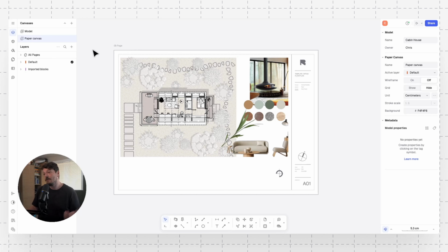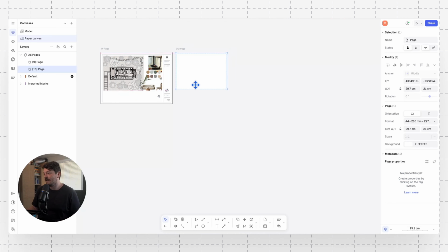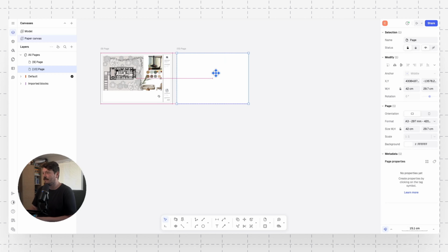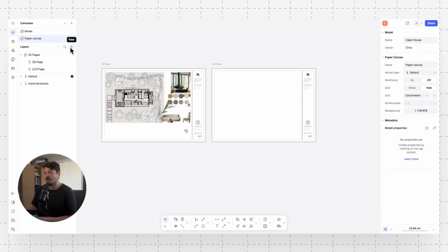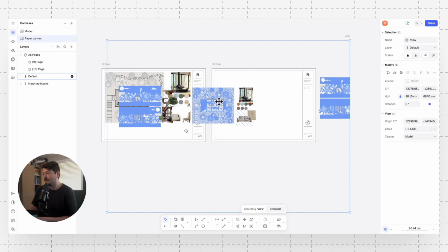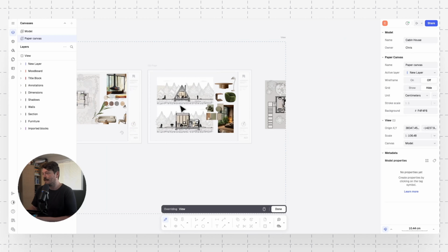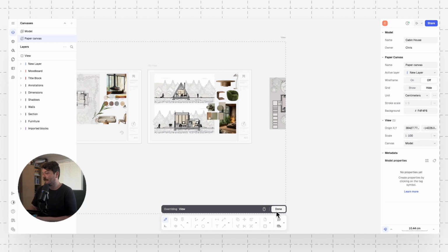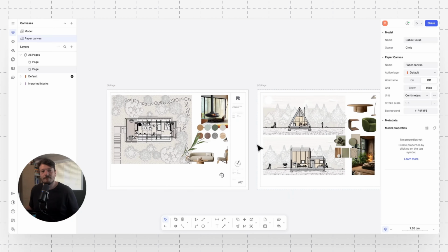And if I wanted to create a new page, I could just do the plus sign, again, create a new page, drag that over here. We can snap that into a nice grid. Again, we can set the scale, so A3. We can copy the title sheet across, and then I can create another view. So again, plus, view from the model, double click into there, and go over to the section. We can set our scale to 1:100, come out of that. Again, press command, and we can then crop our view, and then we have two very attractive presentation pages.